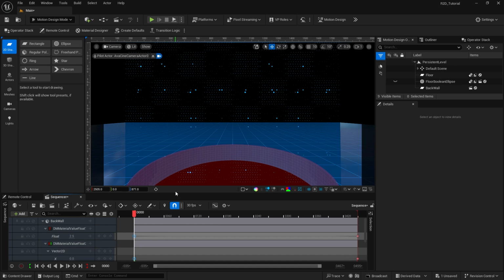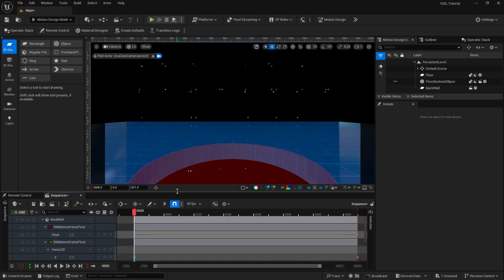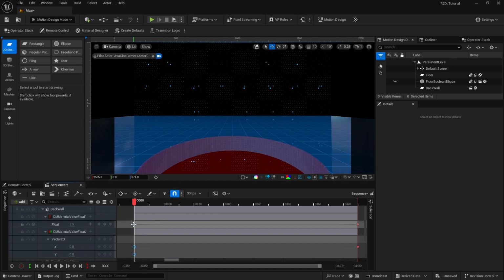Now, all of those keyframes, I want to make sure that they're linear, because right now what they'll do is they'll start off slow, ramp up in speed, hit a maximum speed right there in the middle, and then start ramping back down. So I want them to be constant across, so I'm going to select all of them, and actually that bottom one there I don't need, but select those four, right-click on them, and go to linear. And so now they'll be constant.